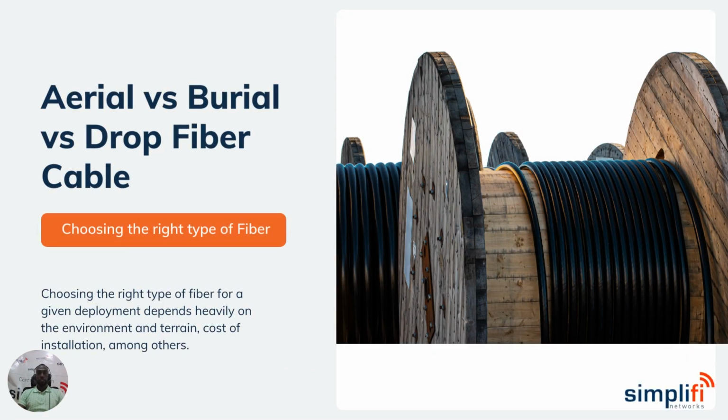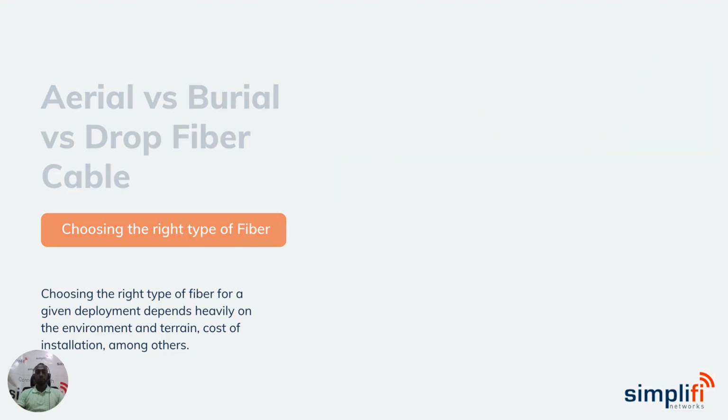Then we also have differentiation in terms of the kind of deployment that you're going to use your fiber for. You have what we call aerial fiber, you have what we call buried fiber, as well as drop cable. Each of these has circumstances when it's best suited, depending on the environment you're trying to deploy in, or maybe you don't have right of way to dig, or you can't plant poles, things like that.